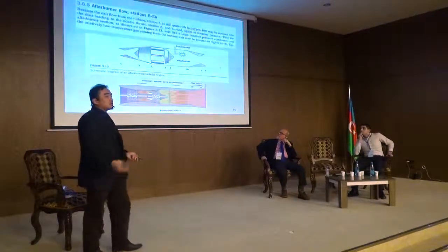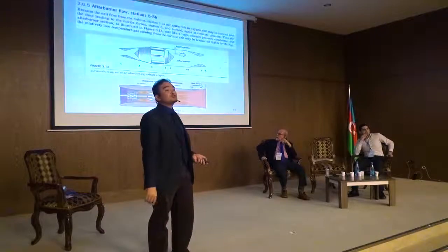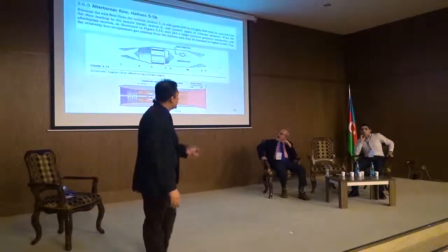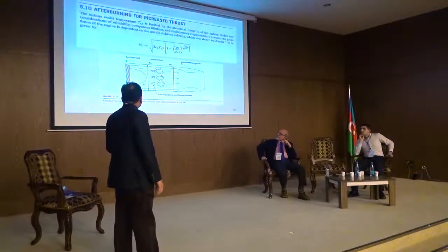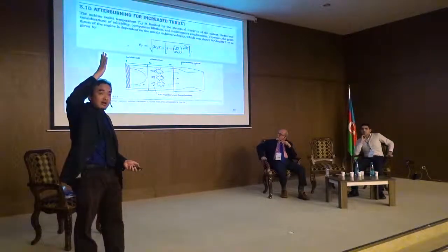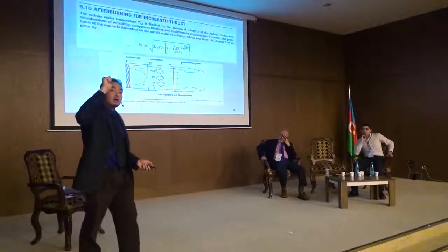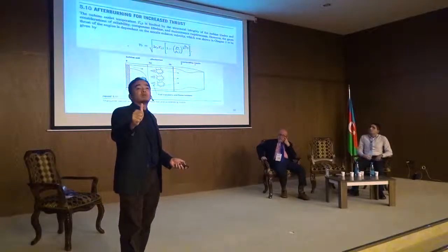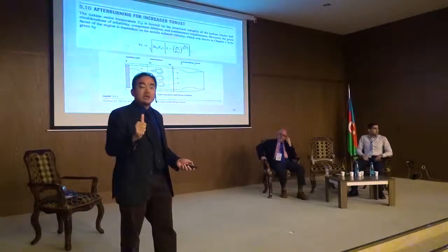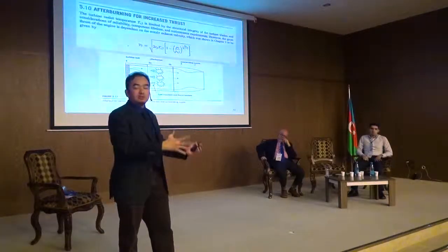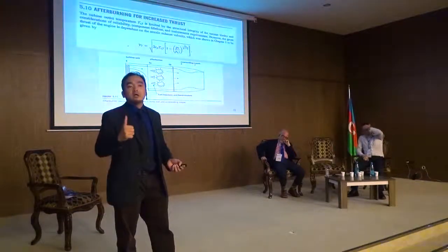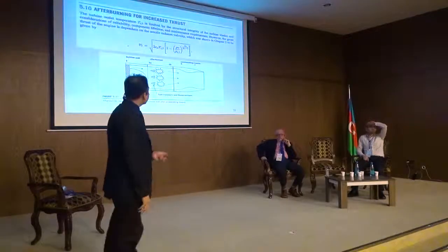So, as I said, the Concorde or military supersonic jets have afterburner applications. Again, the velocity depends on the temperature, so you increase the temperature as high as possible. But again, what is the limitation? It is the properties of the turbine blades. Yes, you can add more heat and increase the temperature and the combustion capabilities, but again, the limitation is in terms of the material.